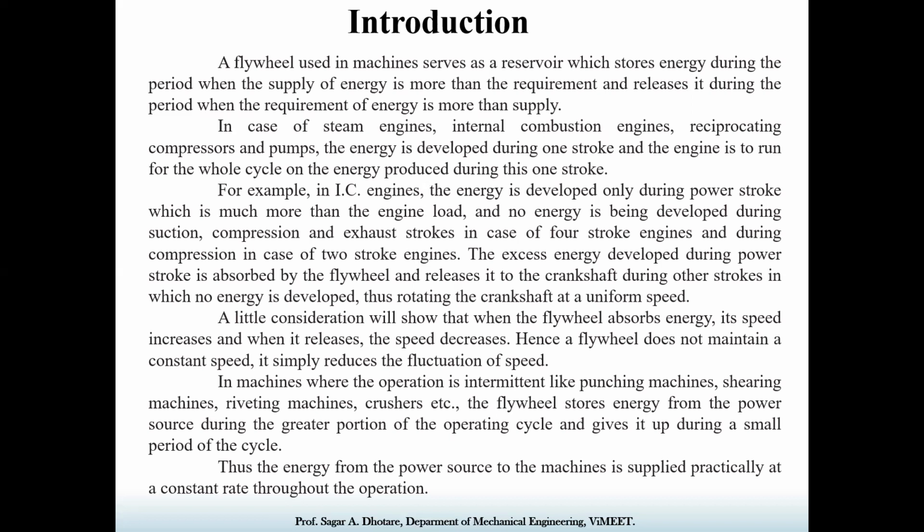Now this excessive energy developed during the power stroke is absorbed by the flywheel and released to the crankshaft during the other strokes. So now there is no energy developed, thus the rotation of the crankshaft at uniform speed.